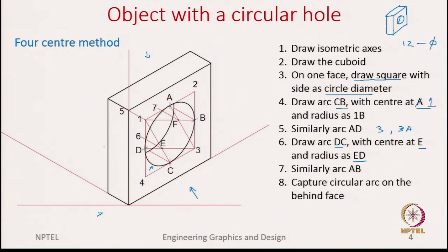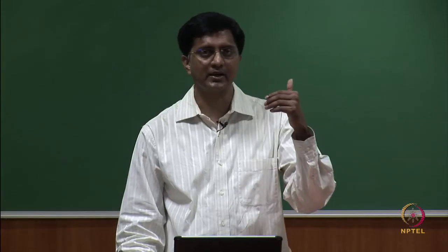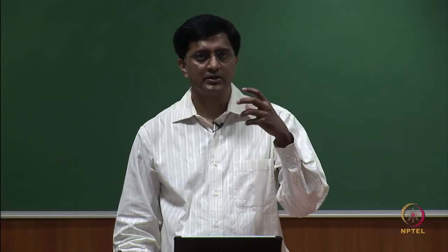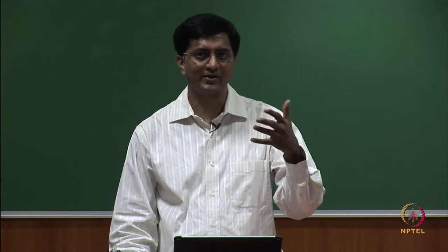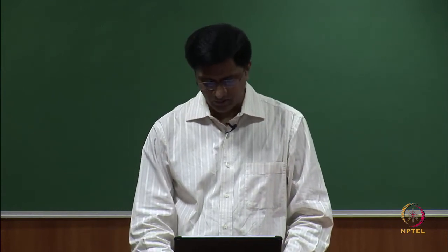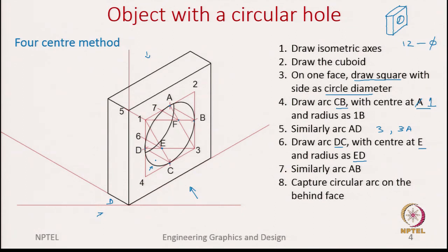Okay. So, if you use the same method, basically we are just drawing parallel arcs now. To draw the parallel arcs, we use this depth axis and draw parallel to the depth axis, and the width of this depth axis is given by this depth of the block. So, using the same method, we are also able to capture the second arc, which captures the circle or the hole in the back face. Okay. So, with this we complete the third example.